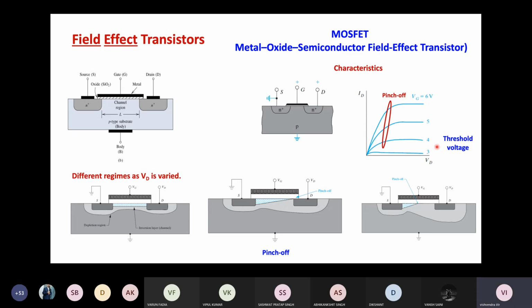And there is this notion of threshold voltage as well. The threshold voltage is the gate voltage, remember, gate voltage at which this inversion layer is formed. So it is the gate voltage at which the current starts conducting in the channel. So below the threshold voltage, yeah.